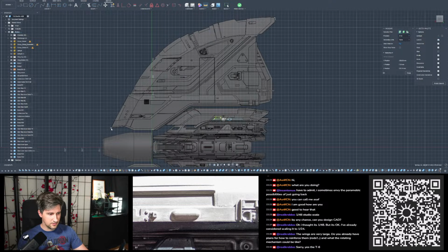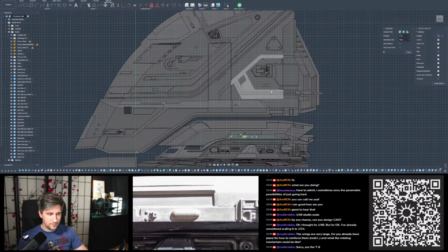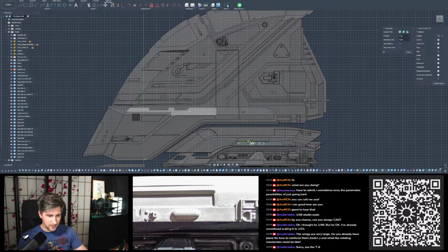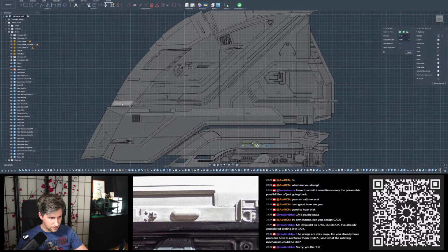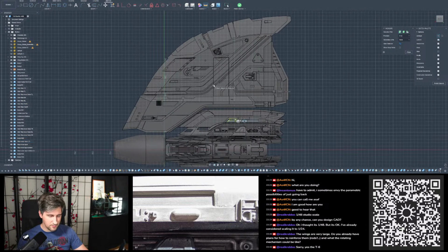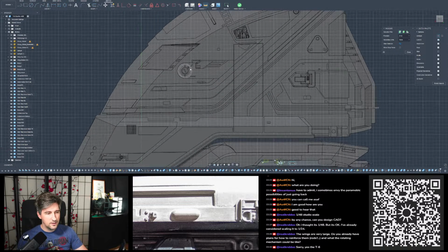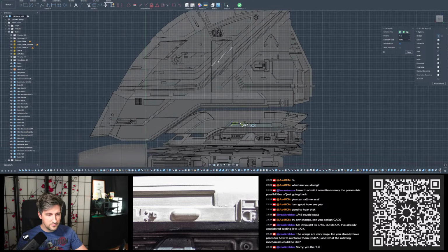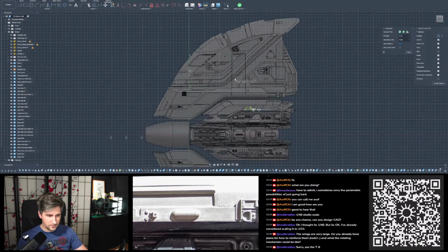When you see, the cross length here is almost 60 centimeters. I have taken some time every once in a while to think about it, but I didn't come to a conclusion on how to split it without having additional seam lines in it. I think it's impossible for this one. So I think I have to make multiple cuts here, and then you have to just filler and sand them. I don't see another way right now.